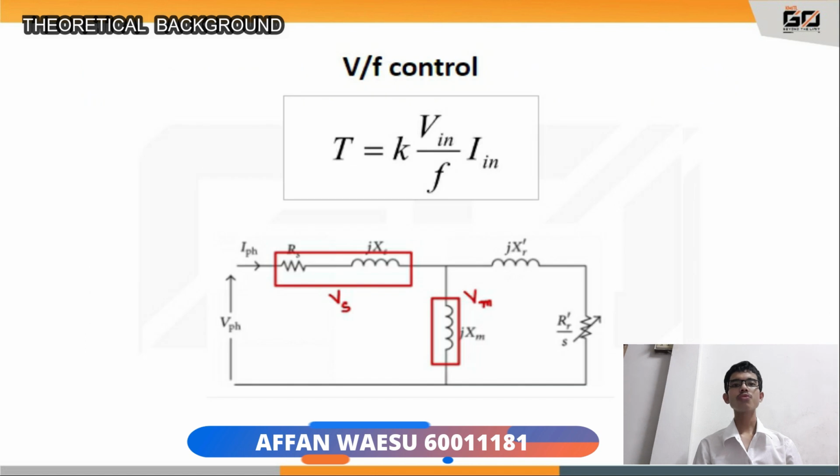The principle of the inverter used in motor control is called V per F control. It controls the voltage ratio to the frequency of the motor through the inverter, maintaining the ratio of the voltage and frequency to stabilize it. This enables us to maintain the torque of the motor at a certain speed range.